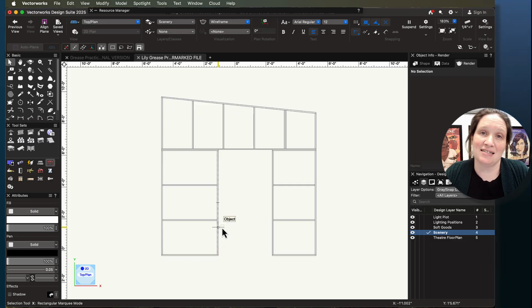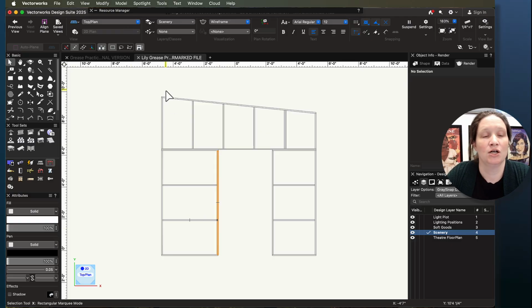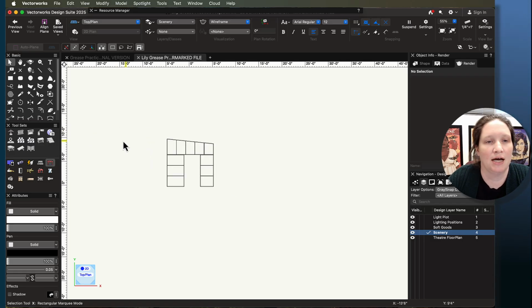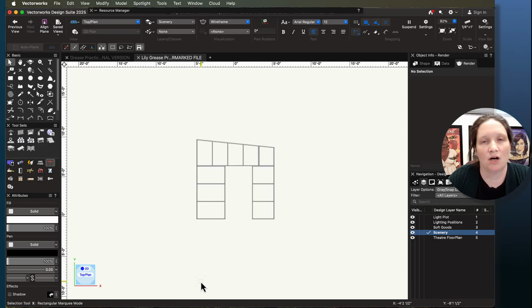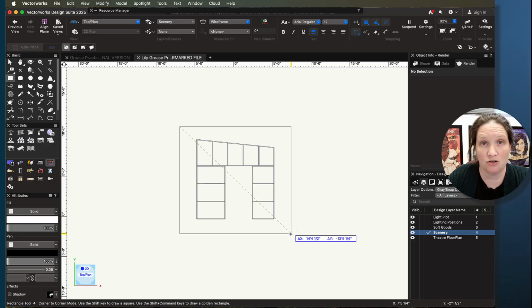And my next step is going to be to take what's called a viewport, which is just a snapshot of all of the things and visibilities as they appear right now on this whole design layer. So if I still had PDFs floating around over here, they would be included in that. If I had more than one thing drawn, it would be a picture of everything, right? To simplify my life a little bit, I'm going to actually create the crop box first. So I'm going to get my rectangle tool. I'm going to draw a little rectangle that just covers the piece that I'm trying to take a picture of.